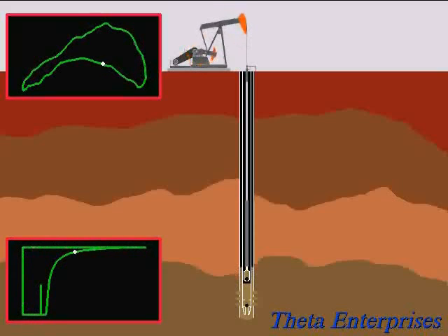So you have a spike that shows up. That's the reflection of the sinker bars. You can see right there the plunger kind of pauses temporarily, and as it does that, it starts to pick up the fluid load, and then it moves and releases it. What's interesting is that you see this when you do a diagnostic analysis of an actual well, but you can also predict this with a predictive program.